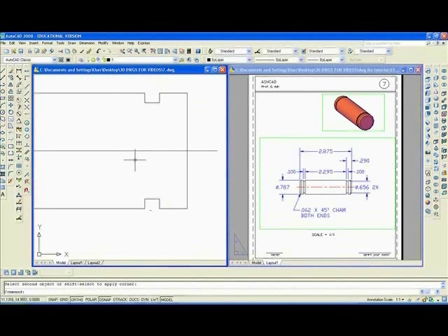And now I'm going to use the chamfer command, CHA, enter. D, enter for the distance. The first distance is 0.062, I'll accept it. The second distance is 0.062, I'll accept that. Now all I got to do is select the two lines, like that, and connect those lines with this straight line here.